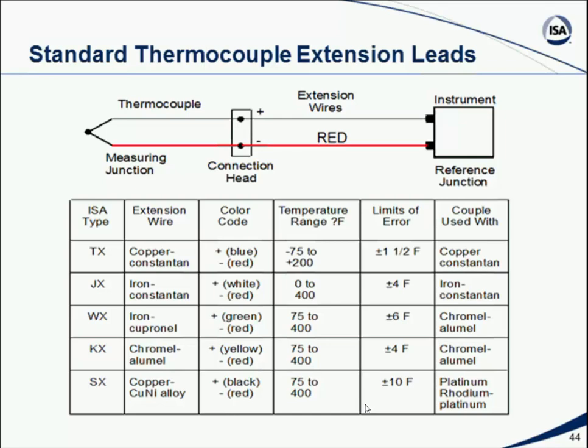connectors. And those connectors and plugs themselves have two pins and two sockets, and they're made out of exactly the same material as the thermocouple. So if you've got a plug-connector combination for a J thermocouple, then one connection and plug is iron and one is Constantan. So, we use thermocouple extension wire to run our leads all the way back to our instrument.